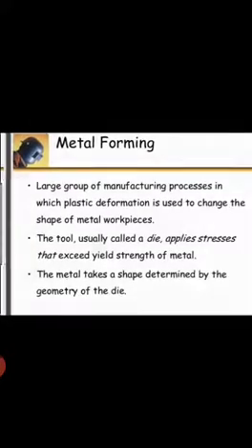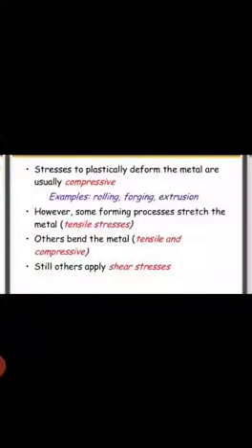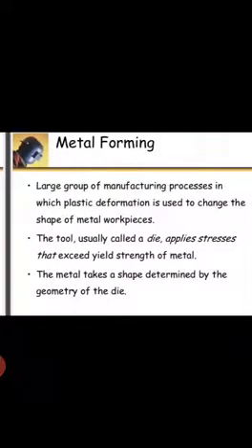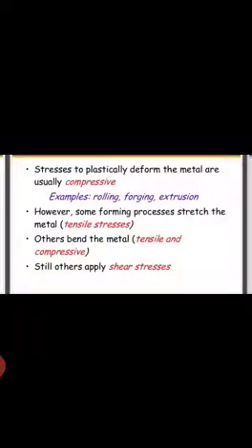The component thus formed through the plastic deformation process has better mechanical properties than those obtained by casting or machining. Since the component is formed to shape without removing any material from it, the wastage of the work material is either negligible or very small, and further the production rate in general is very high with the forming process. Whatever stress or force is applied to cause plastic deformation, we consider it as compressive stress, tensile stress and shear stress.